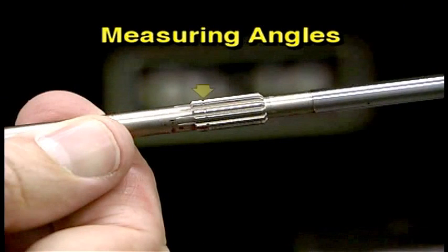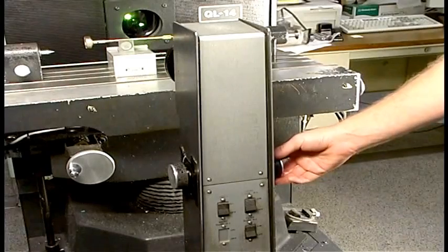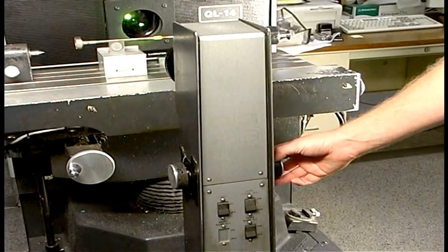The angle of a feature can also be checked, such as this groove. The angle of this groove should be 40 degrees. Mount the workpiece on the stage, then move the table in X until one wall of the groove coincides with one of the lines on the chart. The chart indicates this feature does match the 40-degree specification. The other side of the groove is also checked.